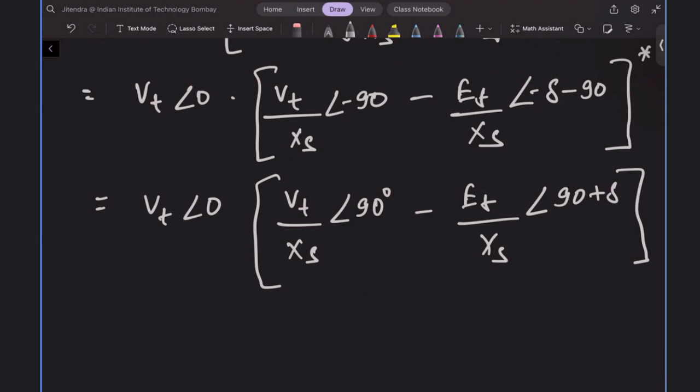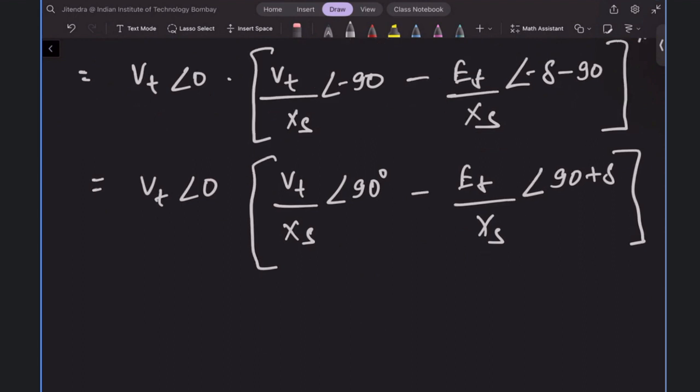And if you are plugging in all the line values only, then you do not need to worry about the factor of 3 or root 3. But when you plug in only phase values, then you have to multiply it with 3 in the end, right? So at the end of every problem, just verify whether you have taken the line values or phase values.